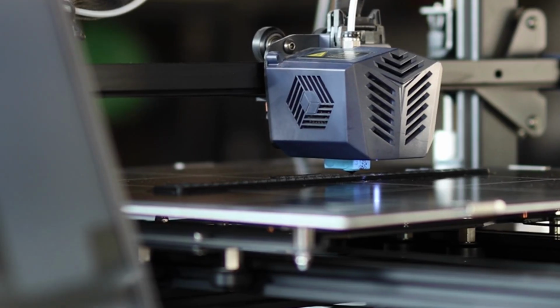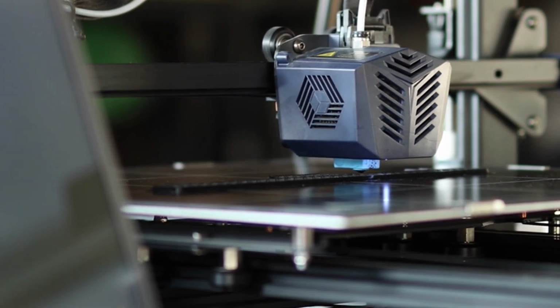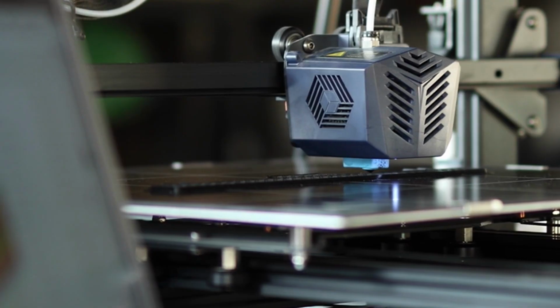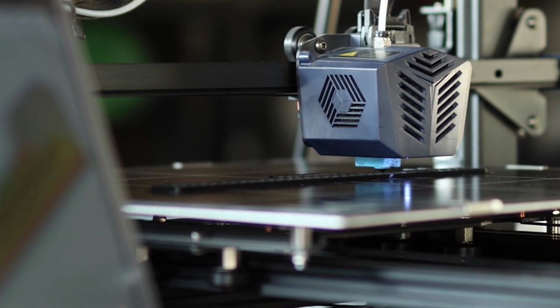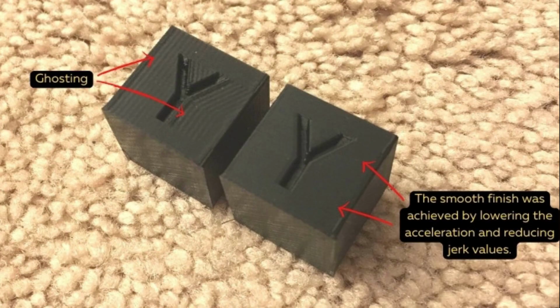For example, when a toolpath approaches a corner, the slicer often slows the printer down, not because the printer can't physically make the turn, but because extrusion pressure needs time to stabilize. If the printer takes the corner too fast, plastic piles up and you get blobs or bulging. This is why features like jerk, acceleration control, and pressure advance exist. They're attempts to model and compensate for the lag between commanded extrusion and actual plastic flow.